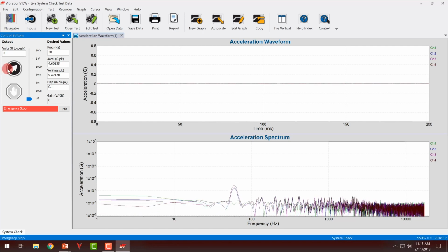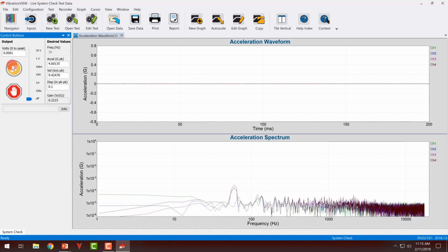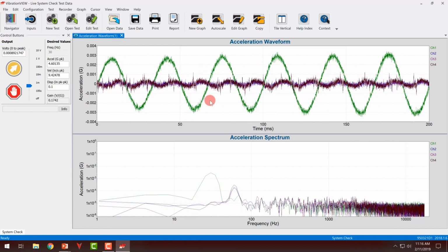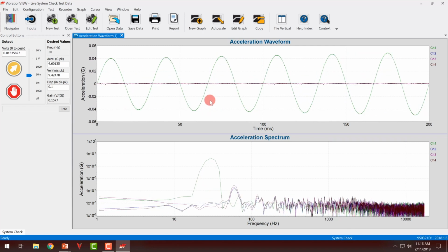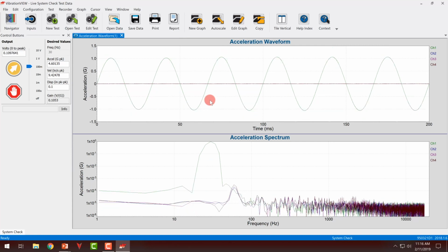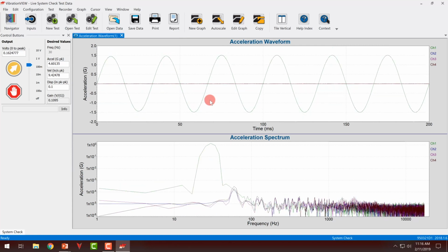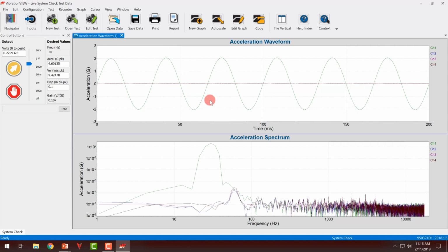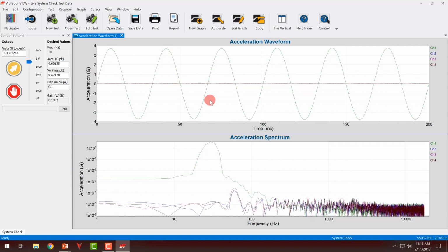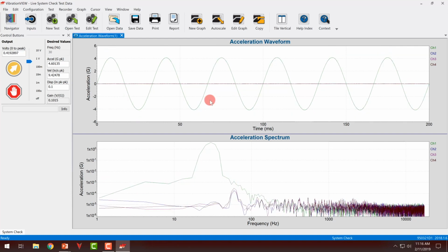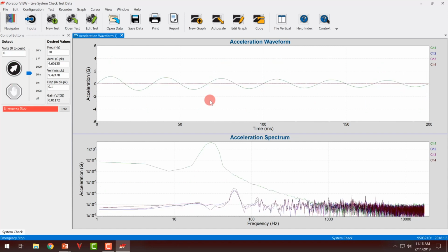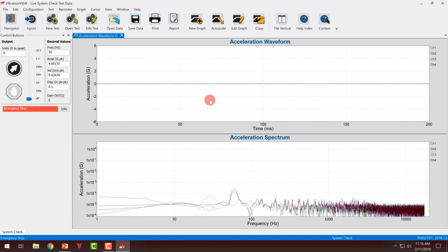So now when I hit the start button, my test in fact can come up because I do not have my emergency stop button pressed. This is a software shutdown. We don't typically recommend doing a hard stop where you actually separate the output relay. That can cause transients, and transients being sent to an amplifier creates some other issues. But once you have this connected, you can simply hit the emergency stop button and the test will stop.